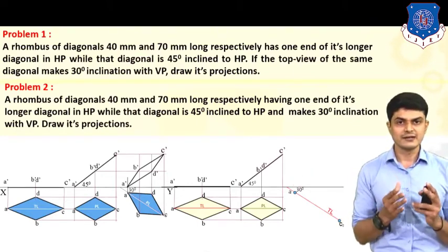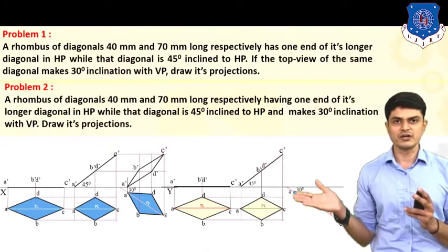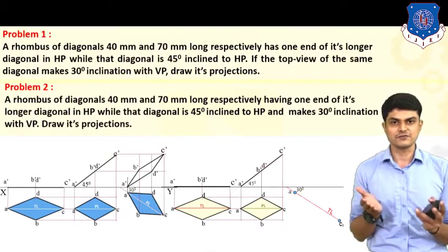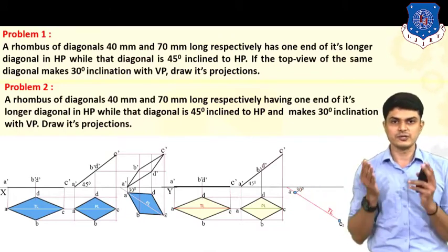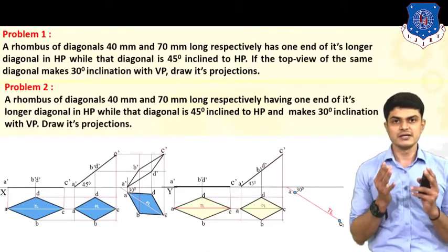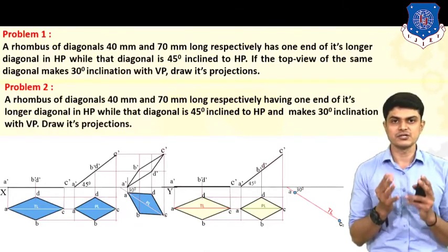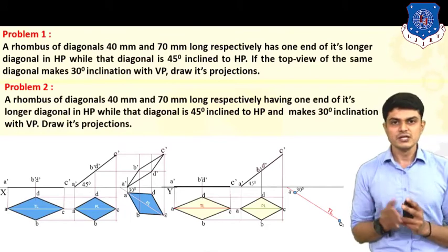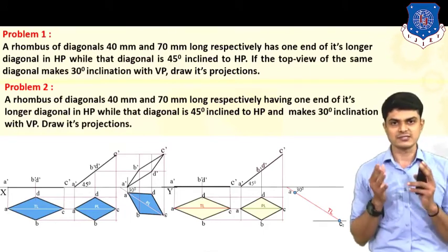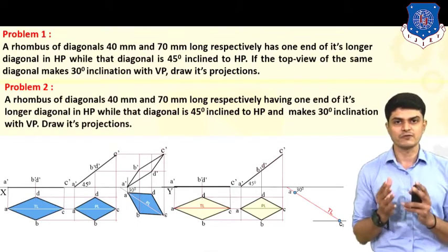Now we know that we always tend to redraw the figure of your second stage, right? So for that, to redraw the second stage figure into the third stage, we need the plan length. So now we need to draw a plan length onto this figure. So first, let us draw the locus from this point C2, and on the same locus we can have the end point of your plan length.